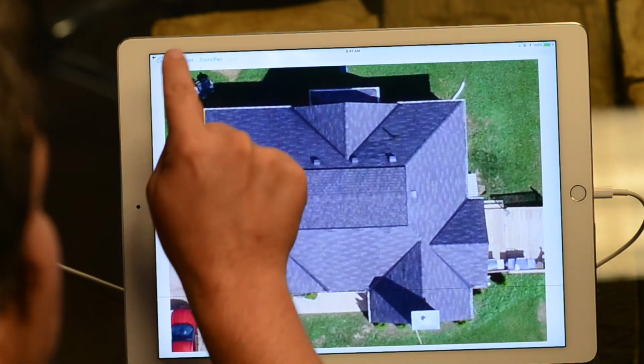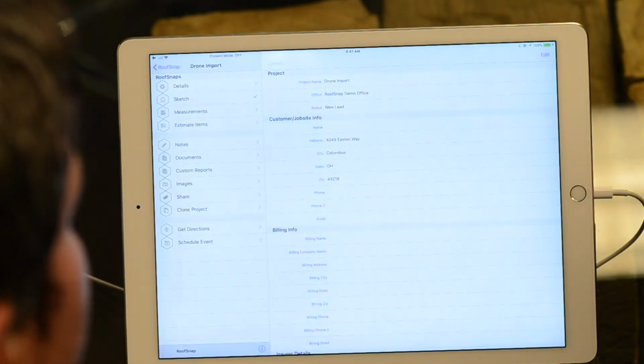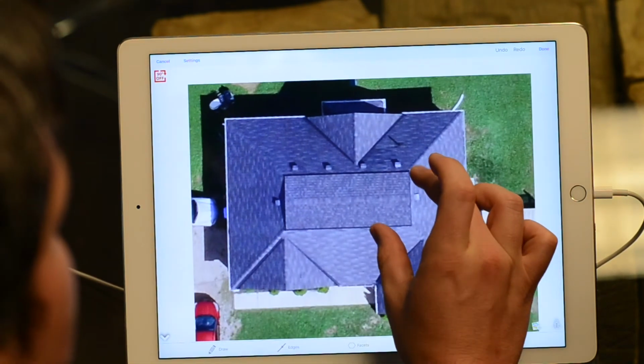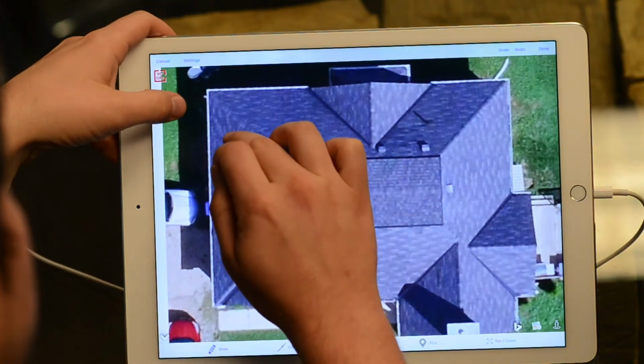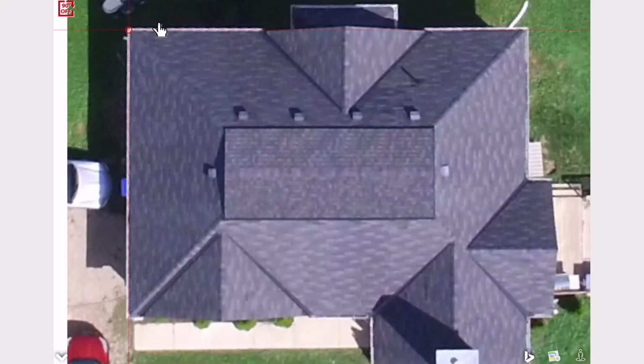Perfect. Tap on the OK button, and then go ahead and tap on the Accept button right there in between Cancel and Pan and Zoom. I want to jump into that sketch. Now we can see that the image is saved to scale. If we draw this line one more time, and if you noticed, I drew it from the center of the gutter to the center of the gutter, so just a little bit beyond, but we are at 45.2, exactly where we want to be.